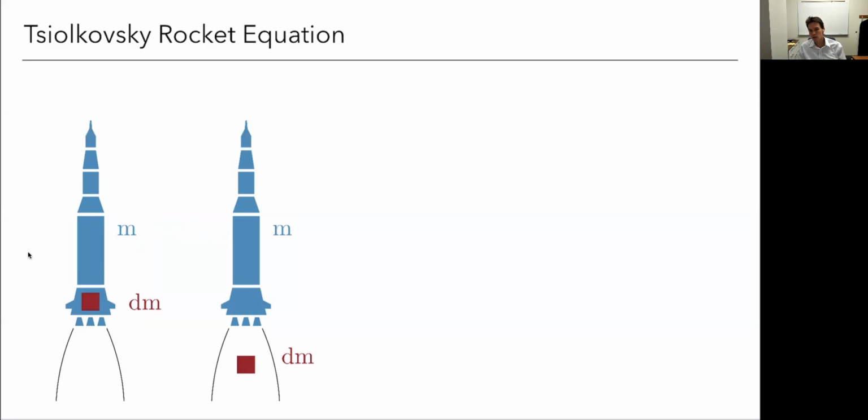We talked about how that's a useful expression to understand trade-offs, and it is. It's still kind of useful, but it's not as good as doing an actual integral, because a lot of those terms like L over D are not actually constant. The same thing's going to apply here. We're going to look at how our fuel is burning and how our velocity changes. And we'll have a differential equation, which in general we want to integrate, but we'll also do a symbolic integration, assuming some things are constant to help us understand better how things trade off.